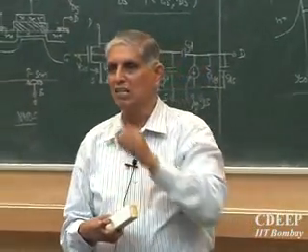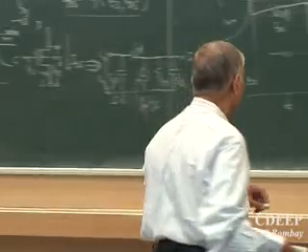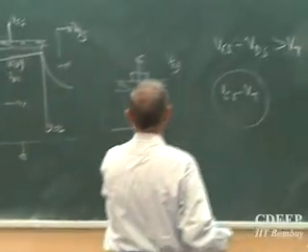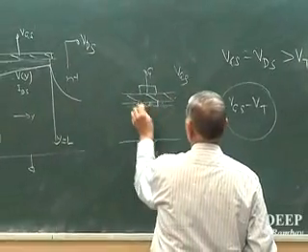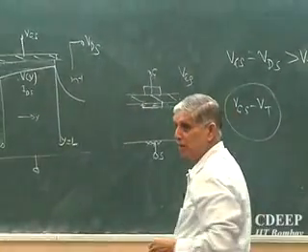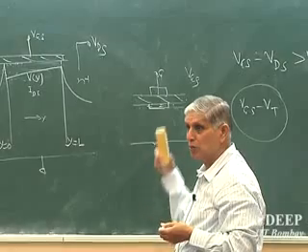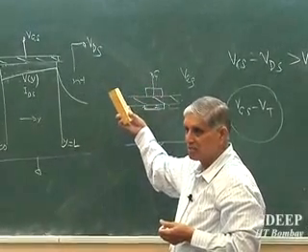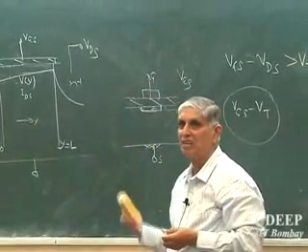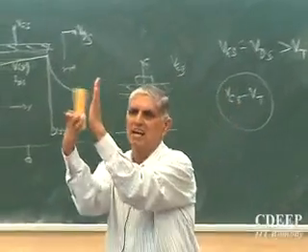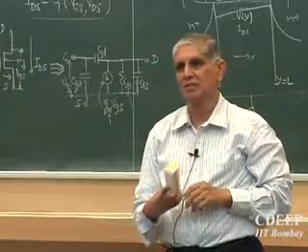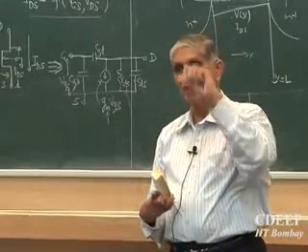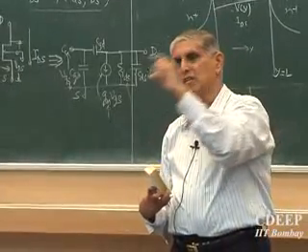So the channel is not like in a MOS capacitor. What did we show there? This much electrons. So we showed it constant everywhere. This may not be true in the case of transistors. So the first thing you should remember is that we have a number of capacitors stacked one after the other, whose VGS are not the same. Is that clear? And therefore, the number of electrons they will invert will be different at different points.